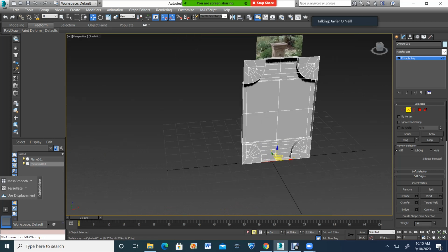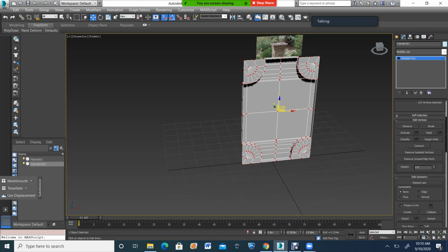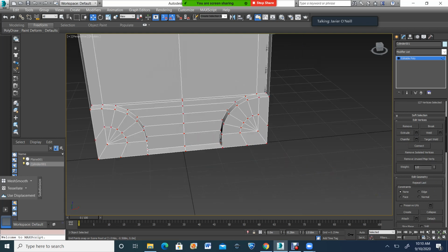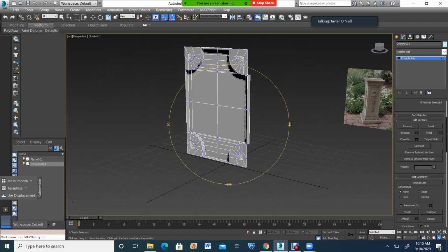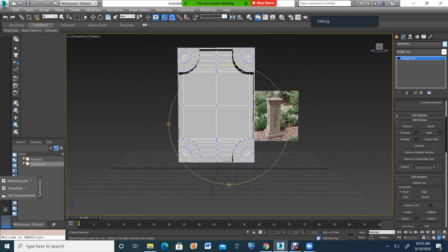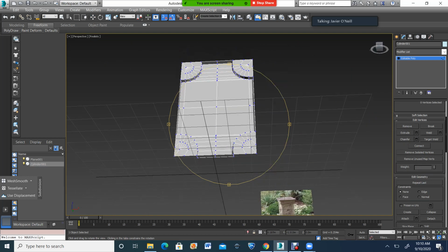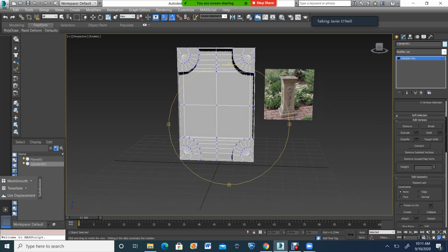And now I want to take all of those meshes, all those vertices that I created, and weld it so it's nothing open, so I select all of them. And if I have weld on at a very low threshold, 0.003 like I said, as you can see, it only welds the right ones. And now we have the first making of that initial shape that we want to work with. So again, I think we're going to do some extrusions so we can get more shape in this item.